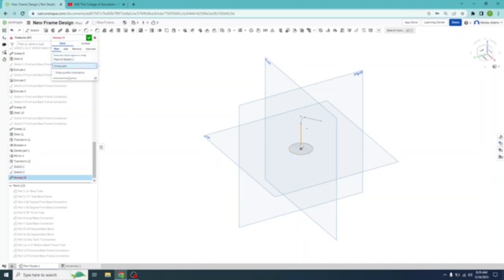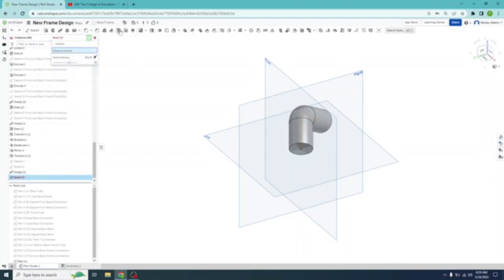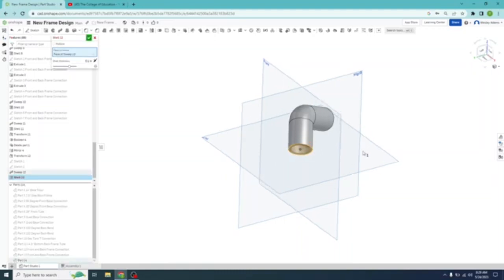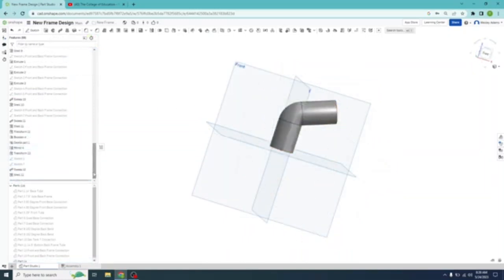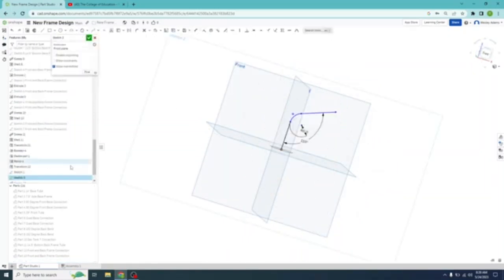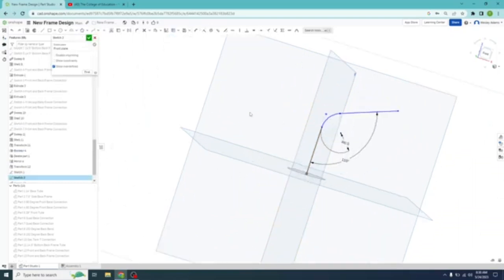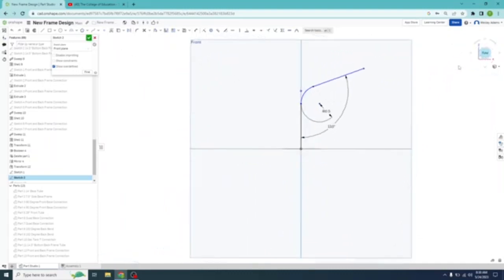Left click on that. We'll select the first segment of the bend, second segment, and the third. Select the hollow tool, left click, come down, select the first part of that circle. We'll select this circle. Back into sketch 2, left click on that. I forgot to change the length of those segments. So we're going to go front view.